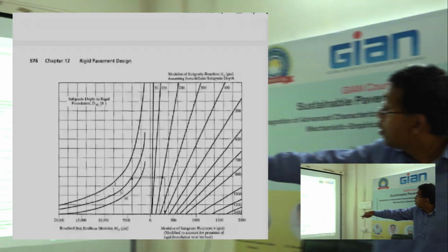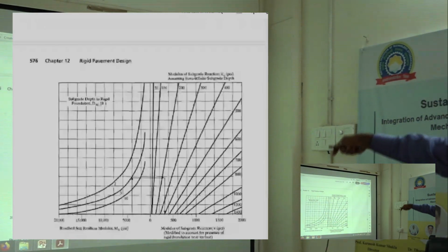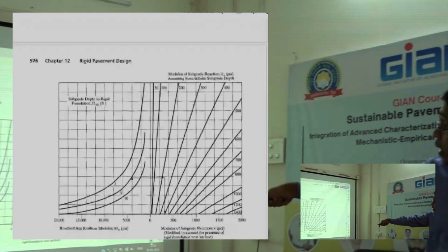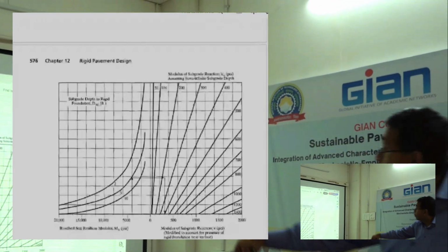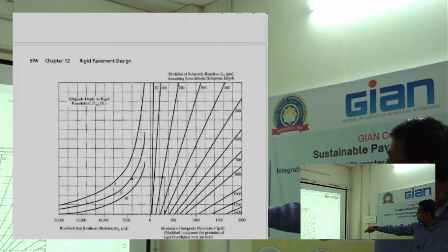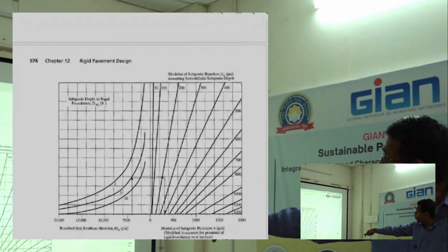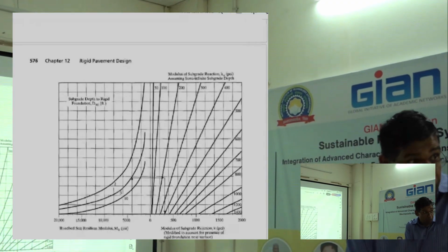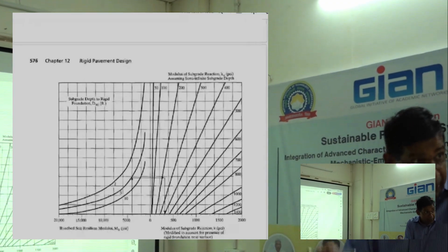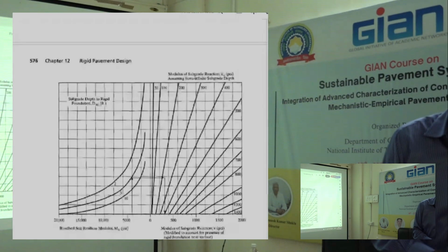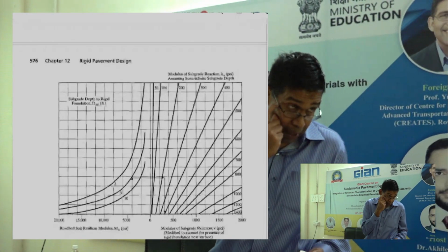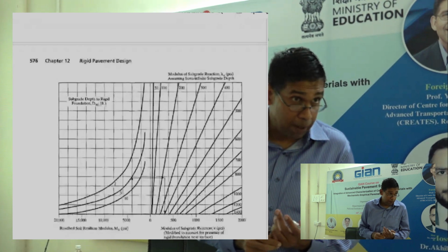Right there, you come to the right, you pick the number from the previous chart, come down and look at the number. It went up from 210 to close to 350, because the rigid foundation is much closer to the pavement than you had anticipated. Does that make sense? That's chart number 2.